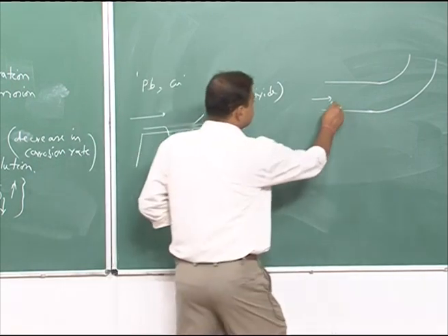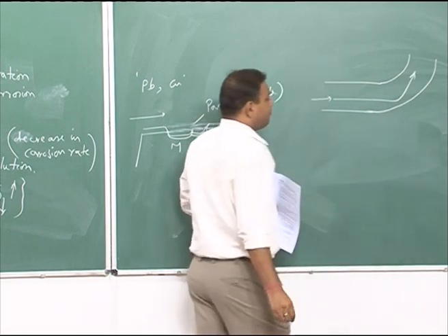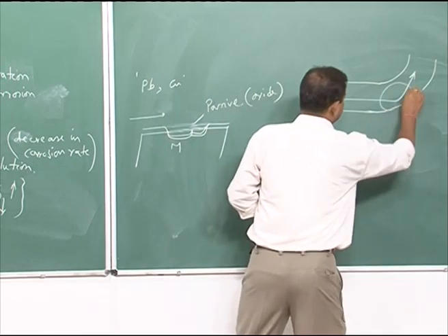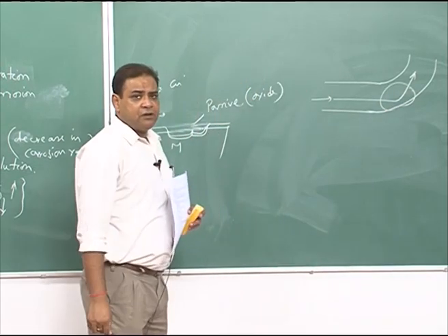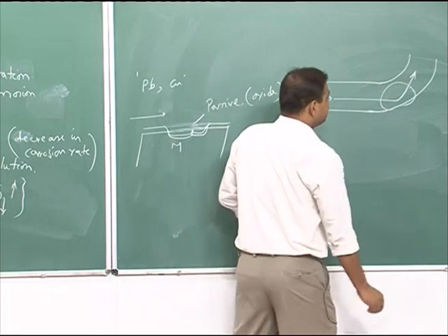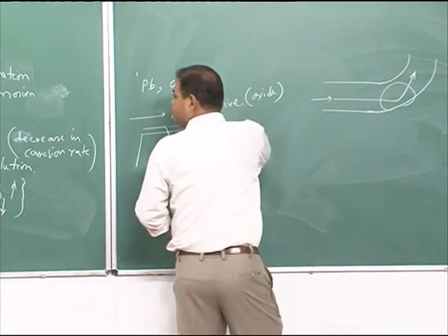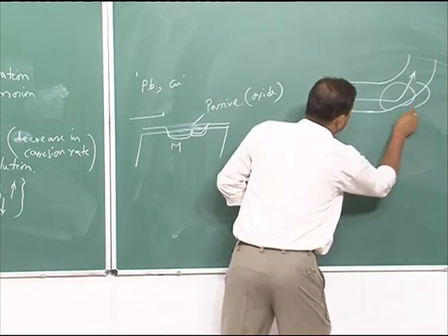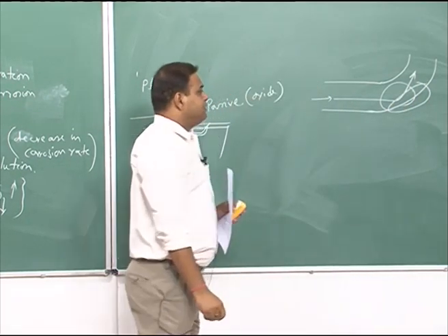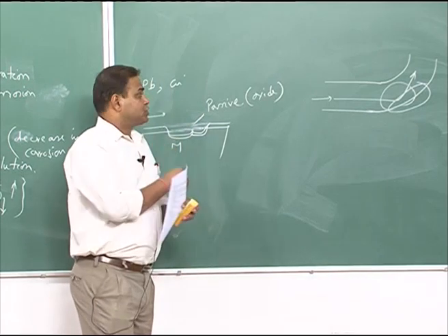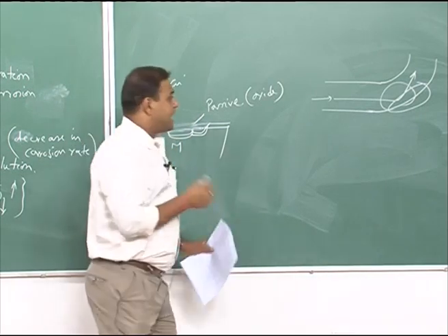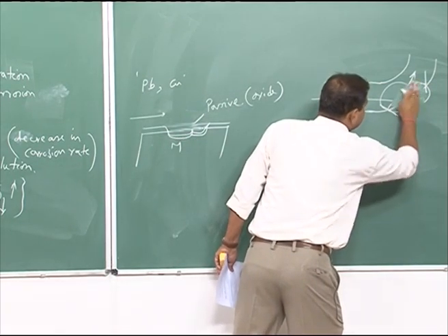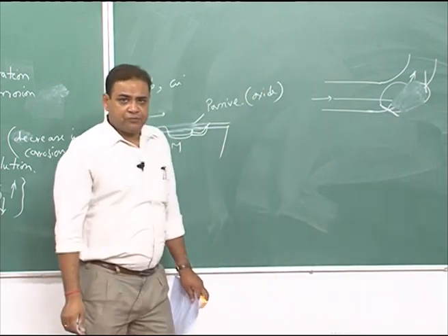But once the solution is changing its path, its movement direction, at that point, in this place there could be huge turbulence, and this turbulence effect is very dangerous if you consider erosion corrosion, and due to this turbulence this part of the metal bend would be susceptible to erosion corrosion to a great extent, and there could be a break in this section wherever turbulence develops.